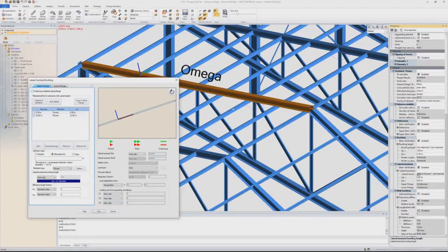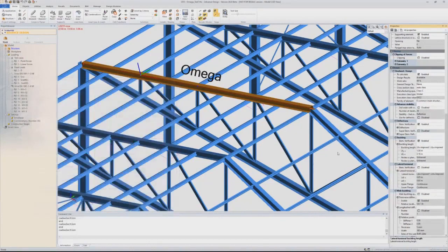Here, it was decided to place some batten plates all along the member with regular spacings and close enough to actually prevent, to turn it into some sort of closed section, and actually it was enough to neglect the lateral torsional buckling effect. So in this dialog, I would simply check this box and consider a continuous restraint to ignore the lateral torsional buckling effects.